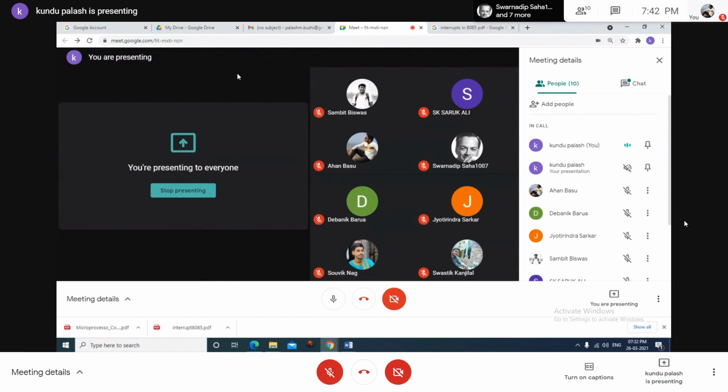There is also another typical situation like the hold state, but that is very complicated. This is a temporary halt state or bus idle state. The normal operation can be resumed upon withdrawing the hold signal, because in the 8085 there are two signals. One is a hold incoming signal, another is a hold acknowledge, HLDA, outgoing signal. But whenever multiprocessors are connected, that means two 8085s are connected, then these two signals are required. That is hold and hold acknowledge. That is different.